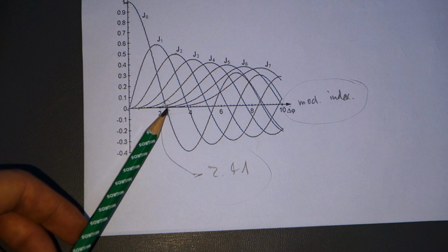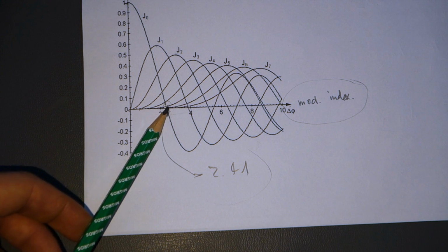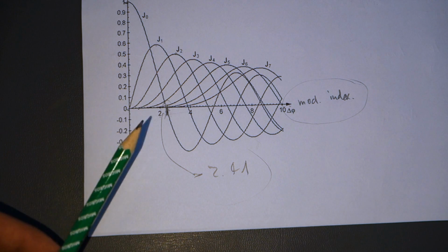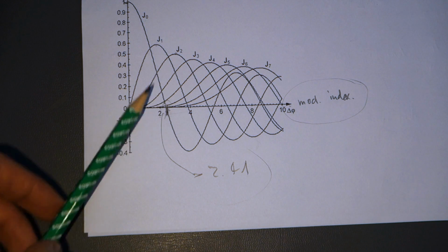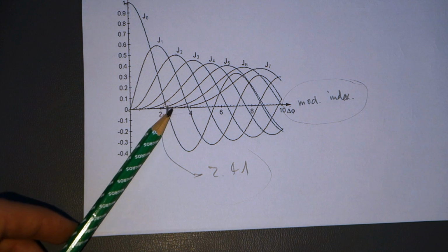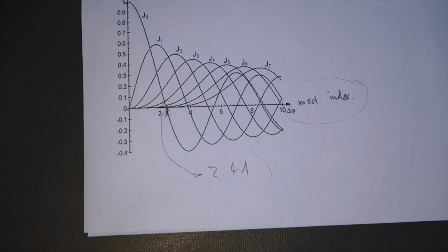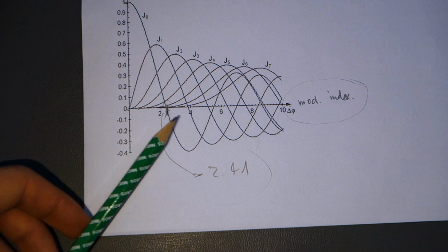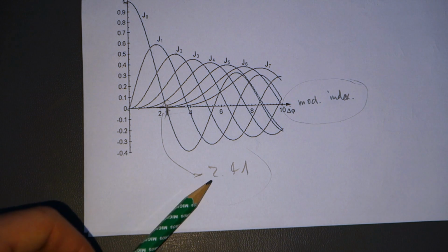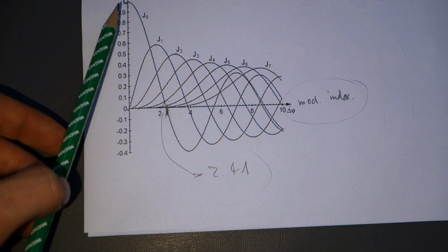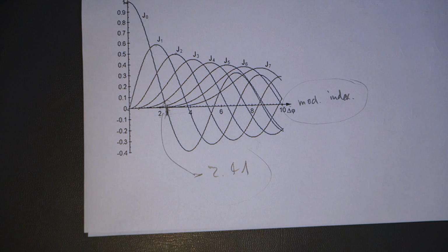And as you increase the modulation index further, the carrier drops down and more sidebands appear, and there is a point where the carrier is 0. When that graph becomes negative, it just means that the carrier starts to rise again with the inverted phase, but whatever. So we're interested in this 0 crossing here, and that 0 crossing happens to be at 2.41. So at a modulation index of 2.41, we have that 0 crossing of the carrier, which we were able to measure during the experiment.